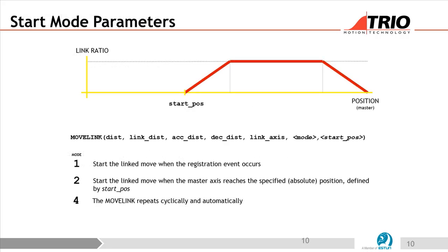The MoveLink can have starting conditions applied to it. So rather than in that previous slide where it was waiting for the rising edge with a basic program, waiting until the input's on has some delay: you wait till the input's on, then you load the MoveLink. Loading the MoveLink takes at least a millisecond, maybe 2, so the MoveLink actually starts a little bit after the rising edge. It'd be much better if the MoveLink started directly on the rising edge.